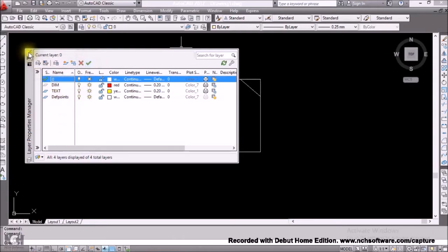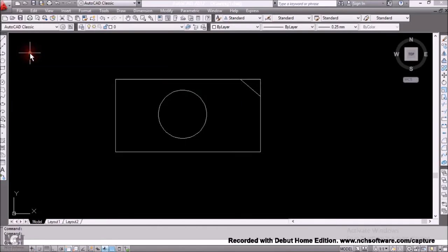So let us delete this. Now remember, we've already created this layer, and we can create multiple layers, assuming we are producing a simple floor plan that has different kinds of information like the blocks, the walls, and the text, the dimensions, and so many other pieces of information. We can create layers for these entities to separate this information and make the work very readable for us to use. So I can start to close this and make a little more explanation of our layer command.